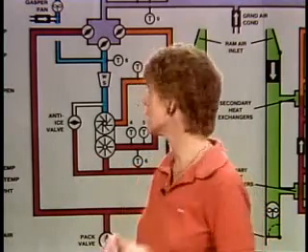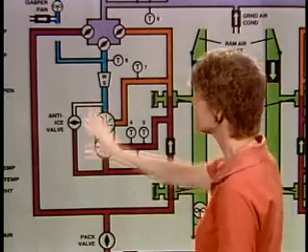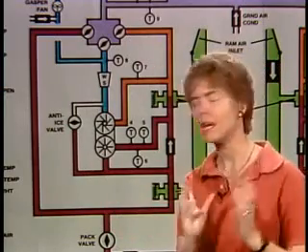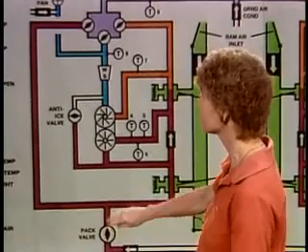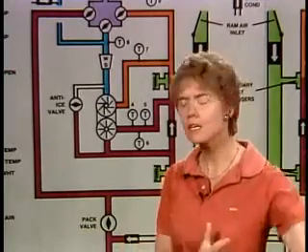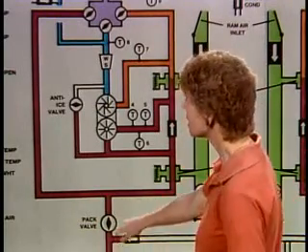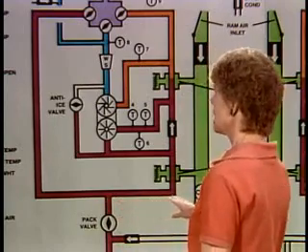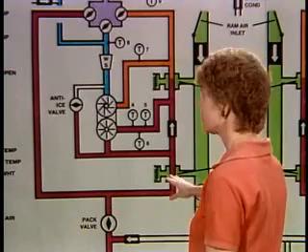To understand those components a little bit better, let's take a look at a diagram of the air conditioning system in a 727. This is the schematic, and the airflow comes in from the bottom. So we have a source of compressed air. In the 727, it's coming off the engines, but again, in other airplanes, it could be an independent cabin system. The hot air comes in from the engines, and it goes through a primary heat exchanger.